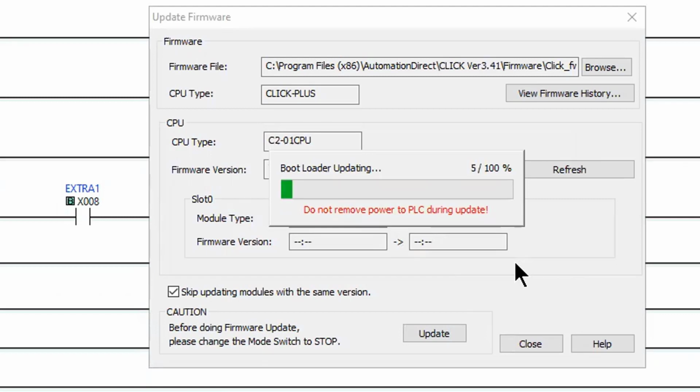Okay, so it's uploading. I'm glad I did it this way tonight because now I'm going through every possibility that you guys could run into on your first time working with these things. Okay, one of the things as you're building your trainer, you get the wiring done and everything. But if you're not quite finished with the wiring and you have your PLC, you can plug it in, provide it with 24 volts, and start downloading and putting things in there. And I'll show you how to set your outputs and force your outputs and everything. And we are almost done here.